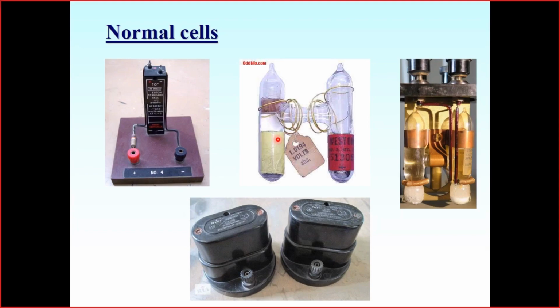They provide a very well known, very well stabilized voltage, and these voltages are well known from the 19th century when extensive electrochemical research was made. So, for instance, for these normal elements, you may see that such elements provide an accuracy of the voltage up to the fourth digit. So the accuracy of these elements is one of the highest, and it actually depends on the purity of the chemical compounds those elements are made of.